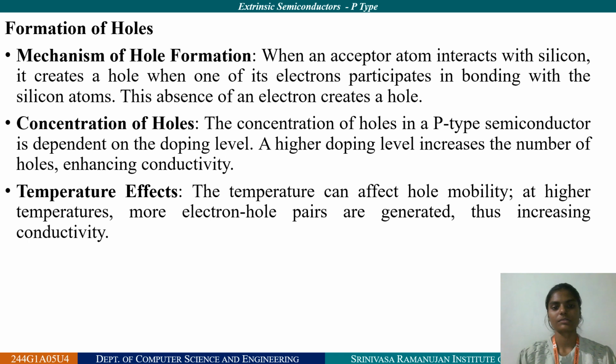Concentration of holes. The concentration of holes in a p-type semiconductor depends on the doping level. A higher doping level increases the number of holes, enhancing conductivity. Temperature effects. The temperature can affect hole mobility. At higher temperatures, more electron-hole pairs are generated, thus increasing conductivity.